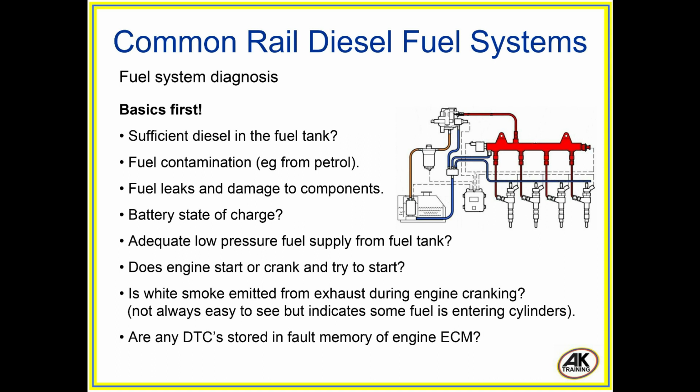Fuel system diagnosis. Basics first. Sufficient diesel in the fuel tank. Fuel contamination, e.g. from petrol. Fuel leaks and damage to components. Battery state of charge. Adequate low-pressure fuel supply from the fuel tank.